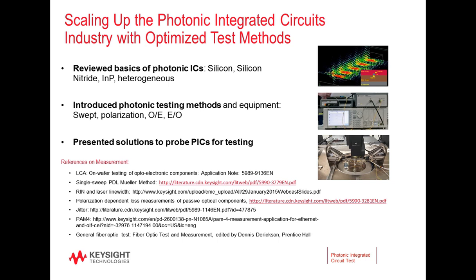So, summarizing the seminar, we reviewed the basics of photonic ICs and gave an overview of testing methods for on-wafer characterization. This included swept methods, polarization, as well as dealing with SFC, deep dynamic range, and presenting methods such as the Mueller matrix method and the all-states method for polarization measurement.